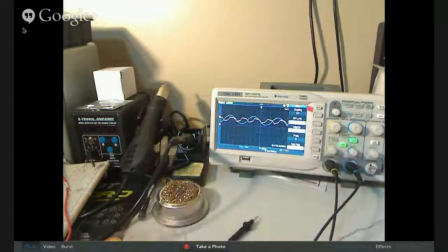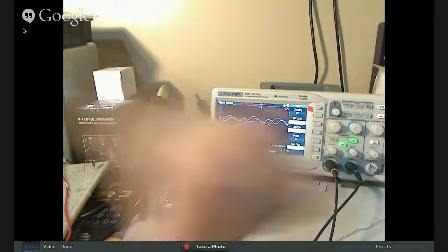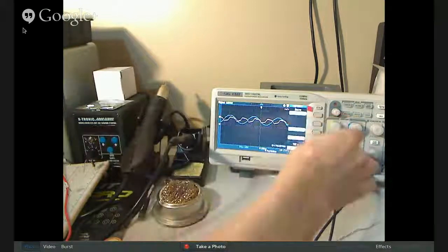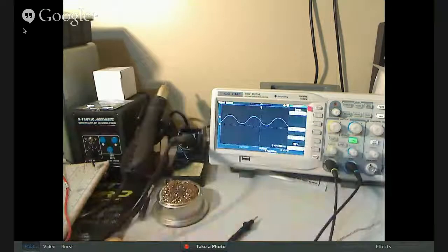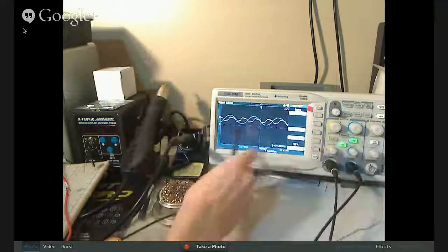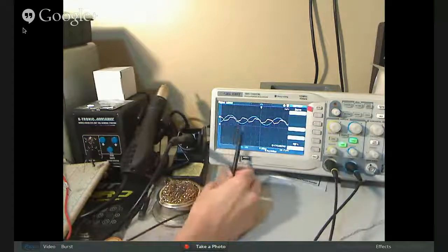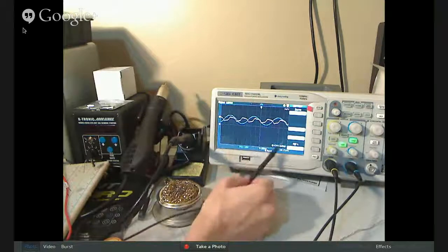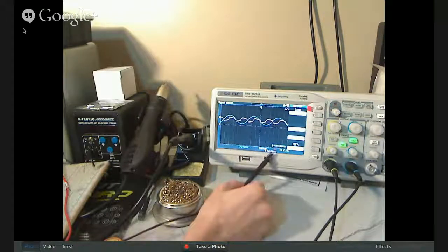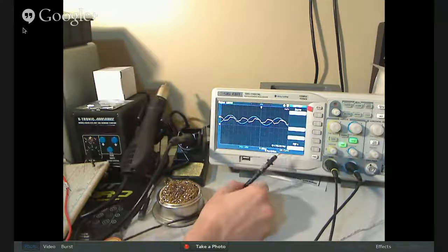There we go. It's not only a proper sine wave now, its period has changed. So since there's a longer period, the waves are longer, and the frequency will be less. It's now reading 750 kilohertz.